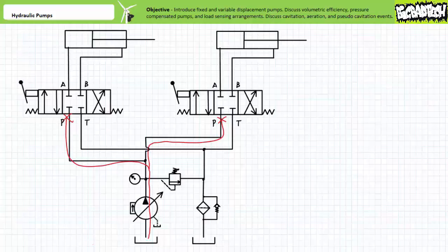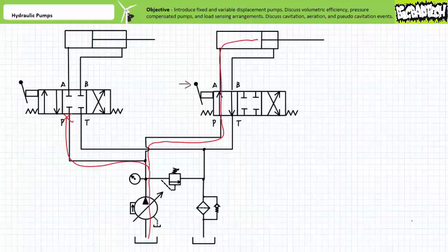Pressure is at the compensator setting and flow is static. The system is in high pressure standby mode. When one of the directional control valves shifts position to move an actuator, pressure returns to a load-induced phenomenon and pressure falls to that sufficient to move the load.